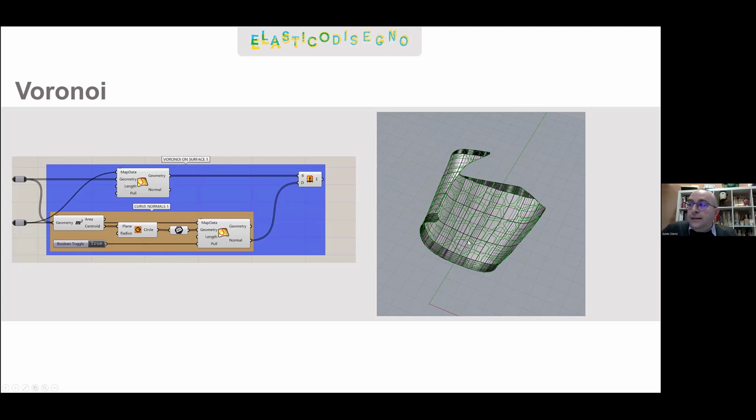and then we had to start cutting, to start generating the solids to use for cutting the surface. In the beginning, we just thought of using these curves to split the surface and then use the solid offset command to do that. But something wasn't working right, and so we had to go through a slightly more complex process to create a normal for each cell.